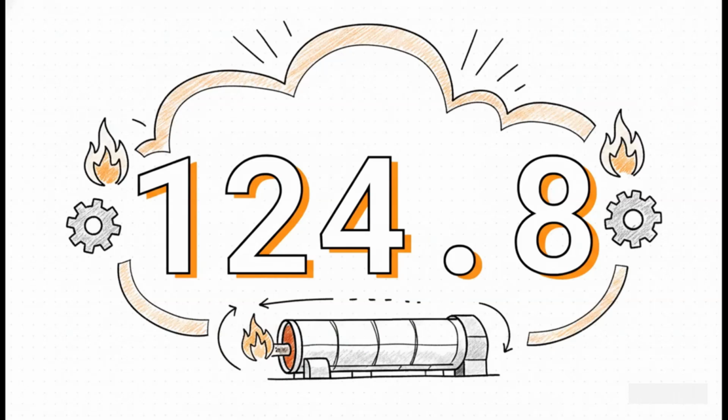Following step 2 of our process, we just add all those fuel inputs together. So 77.5 plus 24.3 plus 12.8 plus 10.2, that gives us exactly 124.8 gigacalories per hour. That number right there is the absolute total heat input supplied to the kiln.